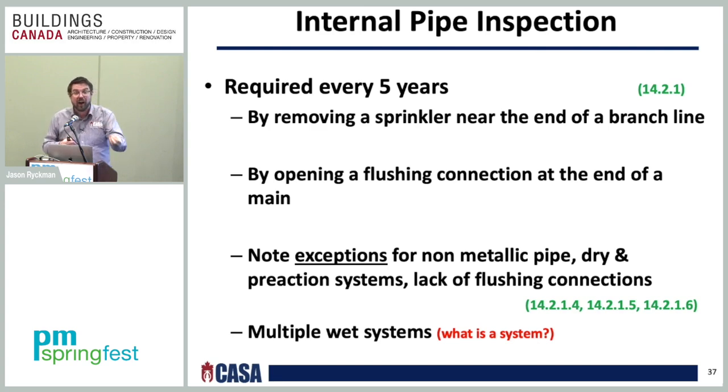Now, if you do find obstructions within the wet system that you are inspecting, then you have to do all of them. So there are some good exceptions to the rule in NFPA 25, which can help you in that aspect.